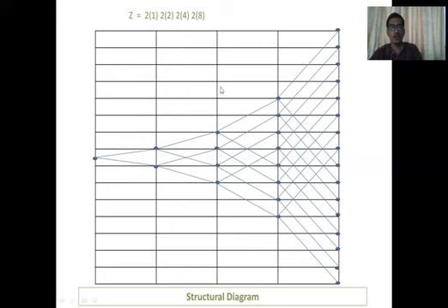Next one is 2^4. These 4 points act as the input and the next shaft acts as the output. Here we have to draw again 2 lines, and the spacing should be 4. So first line, and second line, with spacing 1, 2, 3 and 4. So here we get the second array. Again for this, 2 lines and 4 spacing, for this 2 lines and 4 spacing, and for this 2 lines and 4 spacing. In this way we can draw the speed diagram for the 2^4 step.